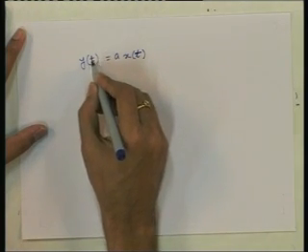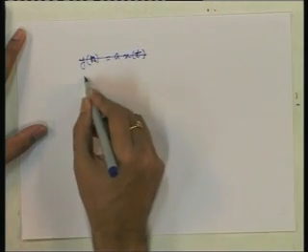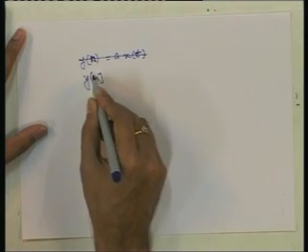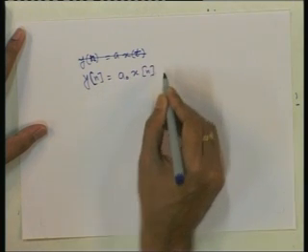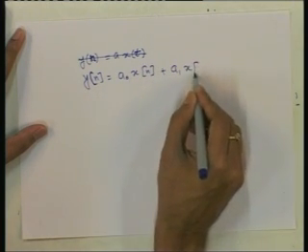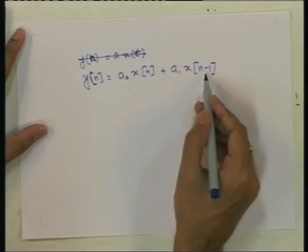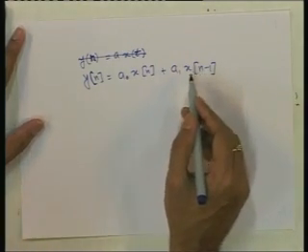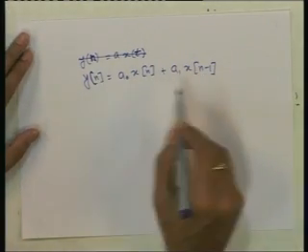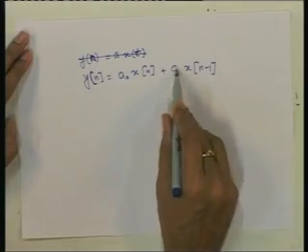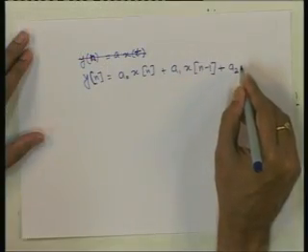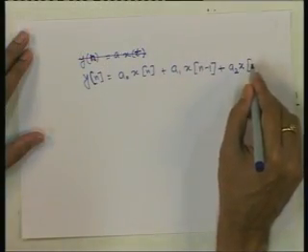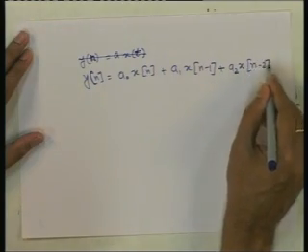say, take the discrete time version for simplicity, say yn is a0 xn plus a1 x n minus 1. There may be another path through which the signal is reaching the receiver with attenuation a1 and delay 1, and then we may have so many other paths, a2 attenuation times delayed by 2 and so on.